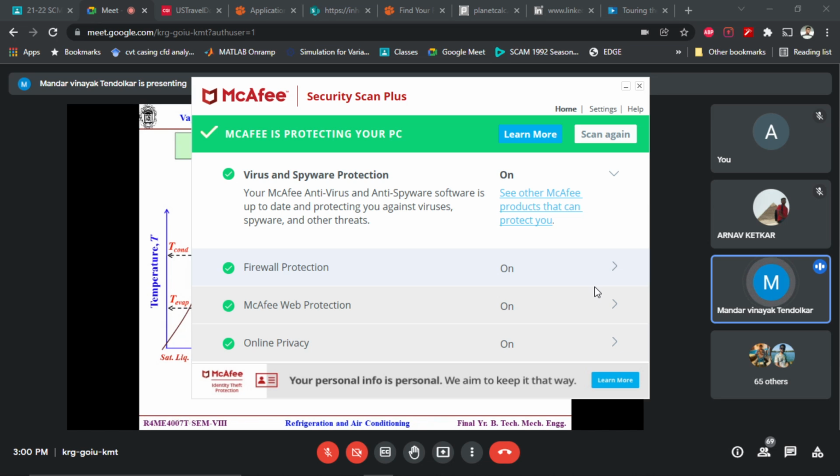So we have to keep this area A2, which is the loss in refrigeration effect, and area A1, which is the extra part for the compressor work, as small as possible. Do you agree? Yes, sir. Fine. Good.